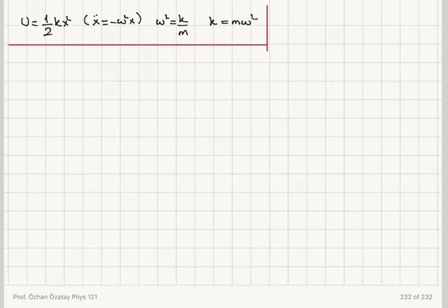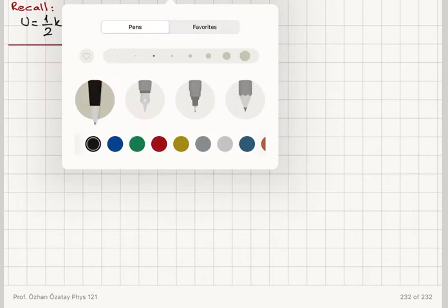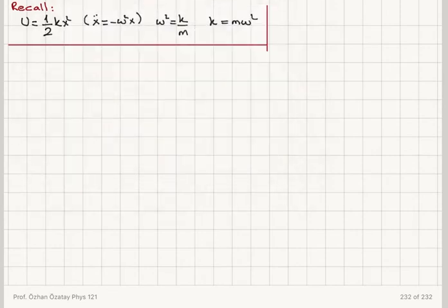so this is basically recalling from my previous study. I'm going to have a potential energy dU that's equal to 1 over 2 omega squared dm multiplied with y squared. So this will correspond to my spring constant k here, it's omega squared dm times y squared. y is the displacement from the equilibrium position.